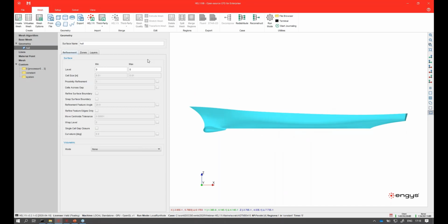And let's start with the linearized free surface solver. For that, we have specific best practices and configuration files in order to create the background mesh, which is probably the most critical part of this simulation study. Having a good mesh is key to getting good results for any ship hydrodynamic solver.